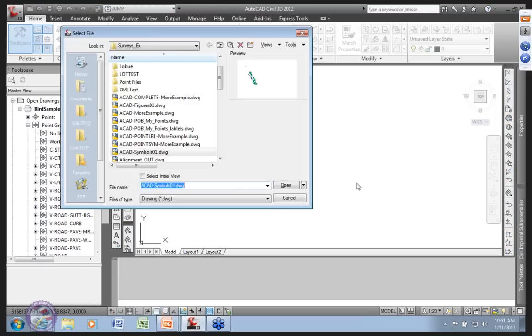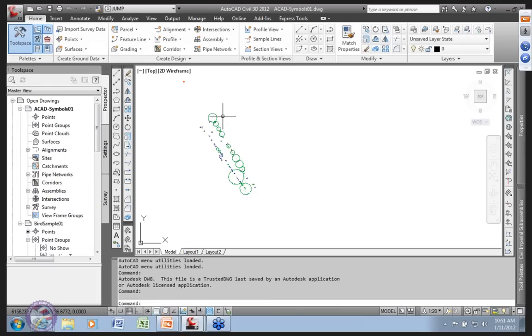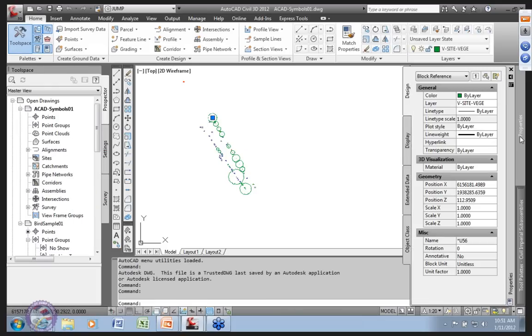Let's open that drawing again. We've got a little bit of processing work to do on this. Give it a second to resolve, and you'll see you end up with a block reference on the right layer as determined by the description key file. It will be layer sorted the right way, all those things. It actually gets XYZ, notice, so I don't want it to have that. Well, there is the flatten command, so you can select and flatten things. You can also grab everything, take all the Z's, and make that Z position 0.